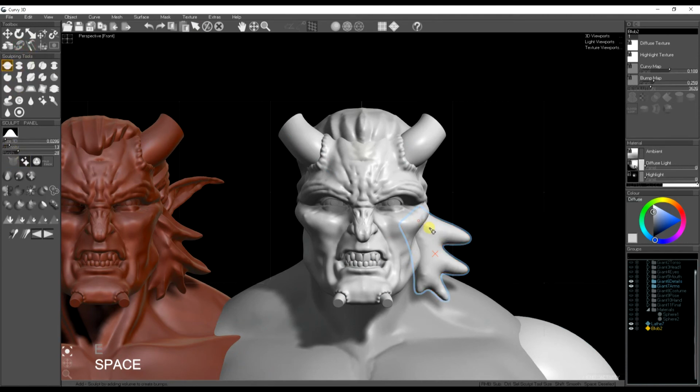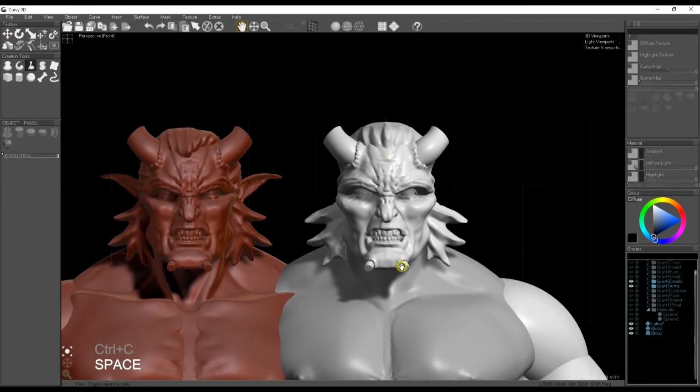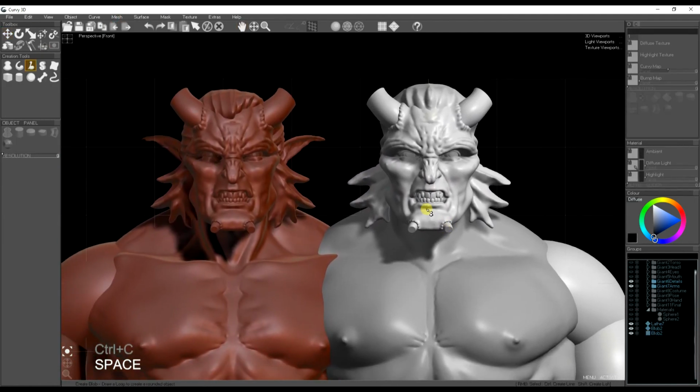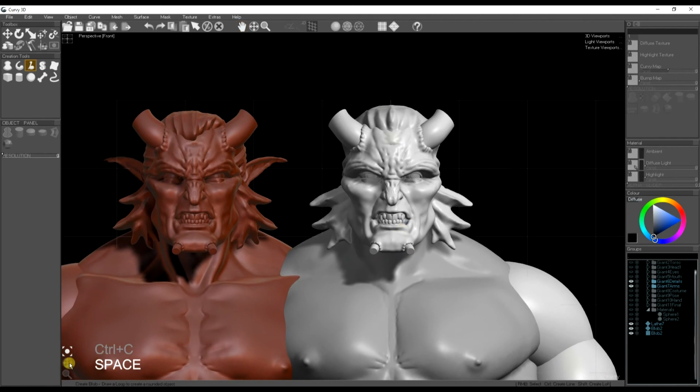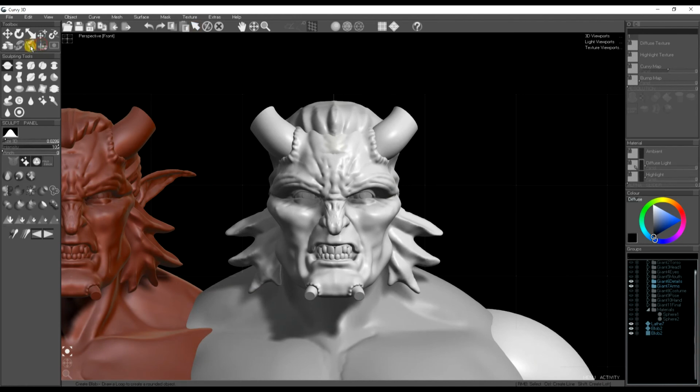And now I'm going to use the add with a bit of pinch to make ridges as if they're locks of hair, using the right mouse button to make creases. I did a mirror on that mesh. Sometimes when you mirror, it turns the object inside out, so you have to do mesh reverse faces to make it pop the right way around again.